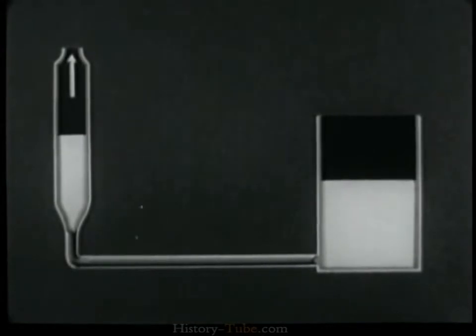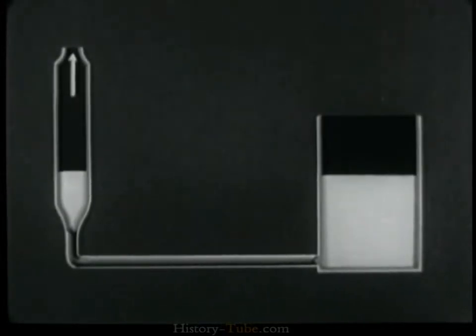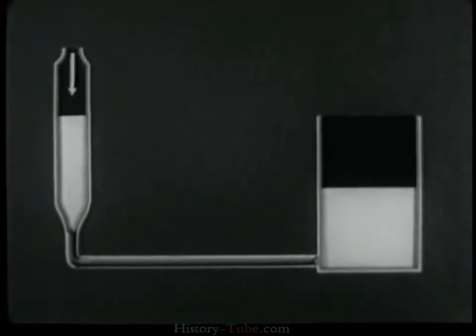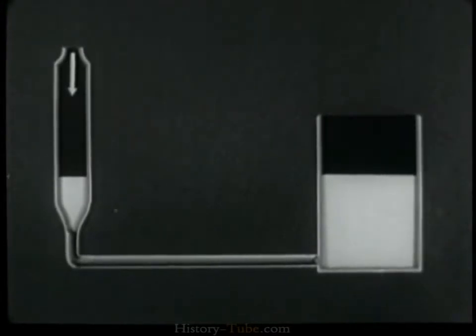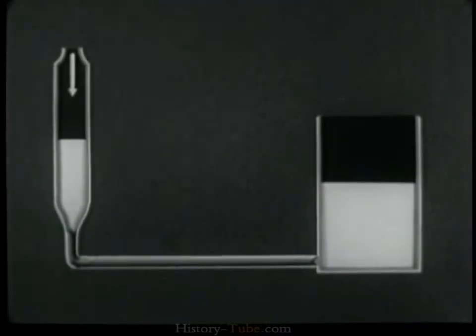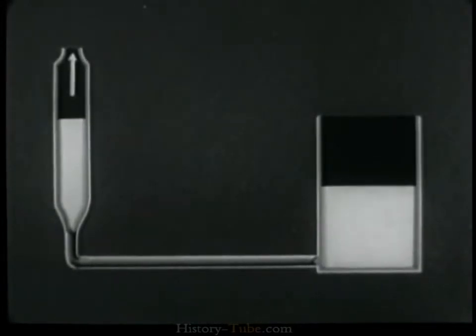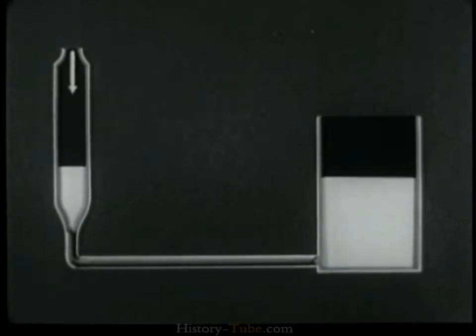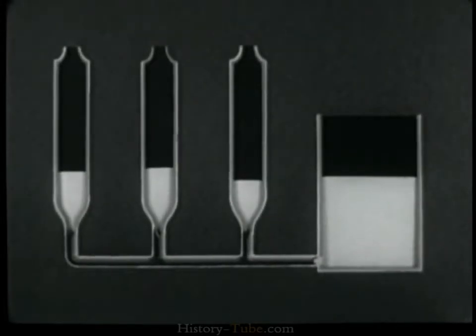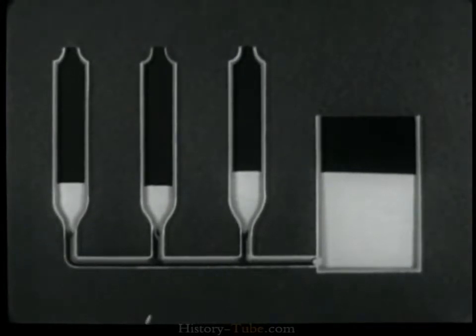If pressure in the tube is decreased, the liquid rises above the level of the reservoir. In a device such as this, if the liquid in the tube is subjected to varying pressures, the level will rise above or fall below the level of the liquid in the reservoir as the pressure is decreased or increased. Reading of liquid levels provides an accurate means of determining pressure differences. Additional tubes may be added, each connected to a different value of pressure, and each will indicate that pressure accurately, regardless of pressures in the other tube.